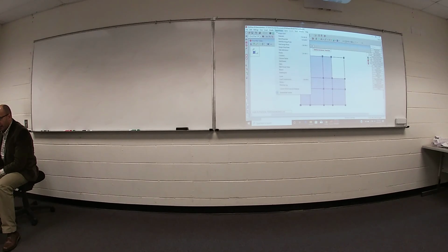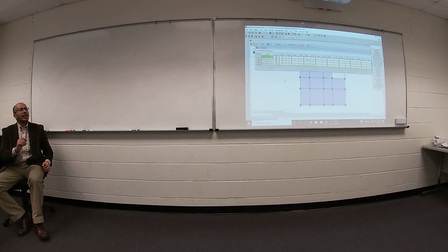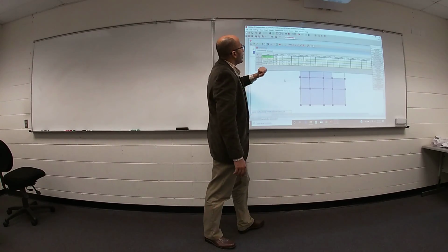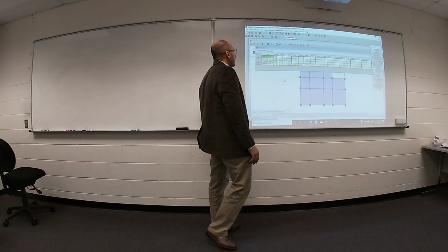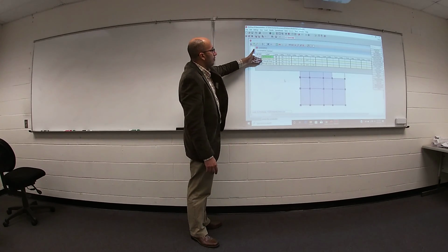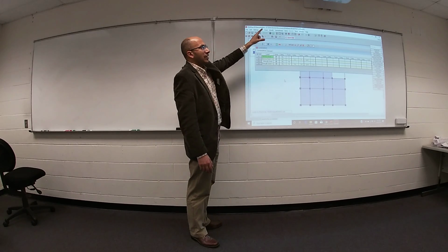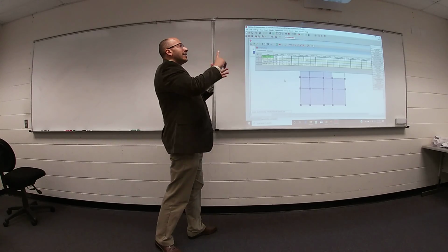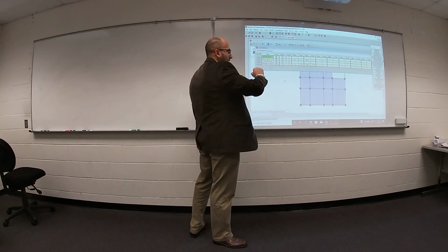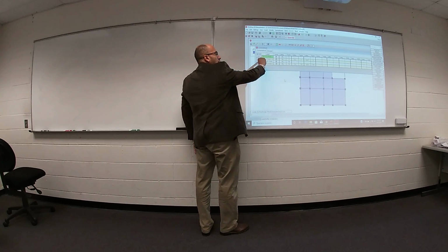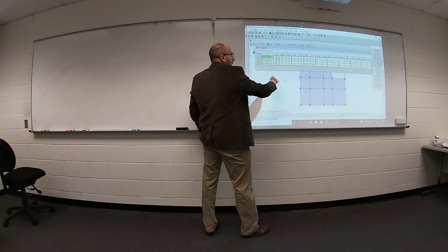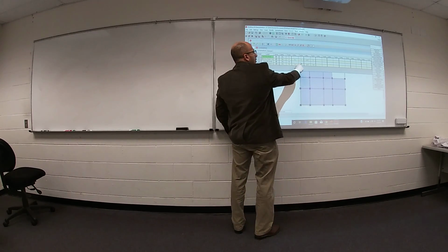But before solving, you have to define something called load combination. Actually, in RISA Floor, you don't need to define anything. Everything is defined for you. If you open the spreadsheet load combination, or just click this icon, load combination, you will see we have 4 combinations. The first two for serviceability, if you remember, serviceability for deflection, for cracks, for vibrations, we don't care. But our concern right now is your strength, your design. So we have first combination, your dead load times 1.4. Second combination, your dead load times 1.2, your live load times 1.6.